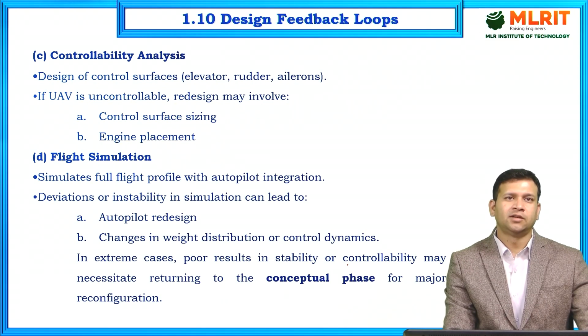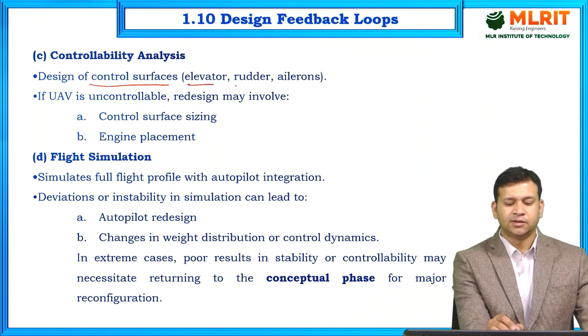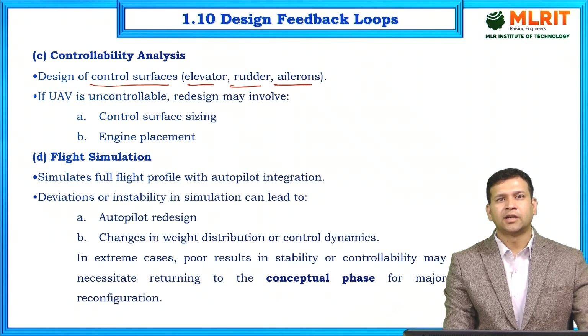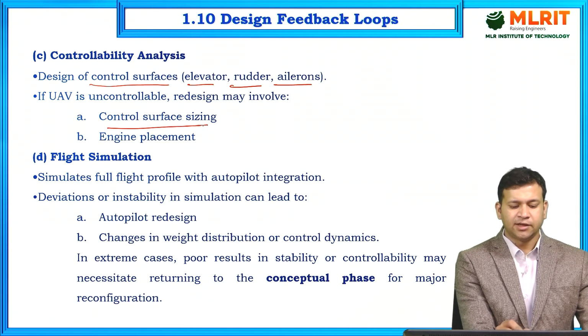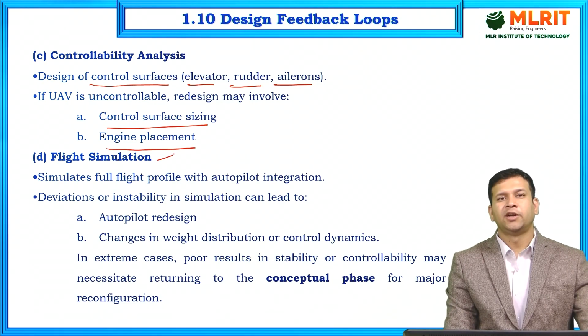Third is control analysis. Design of control surfaces such as elevator, rudder, ailerons. If the UAV is uncontrollable, we have to redesign the control surface sizing and engine placement. Fourth, in flight simulation, it simulates the full flight profile with autopilot integration.